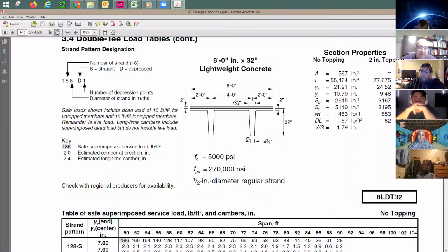The only thing that they're gonna build especially for you is the column. Beams most likely are gonna be in stock, unless you come up with a special beam. When it comes to the span and number of strands, they can do it especially for you. And then you need to wait at least 3-4 months before you have it. So it is not gonna be like, let's order it, I'm gonna have it right now.